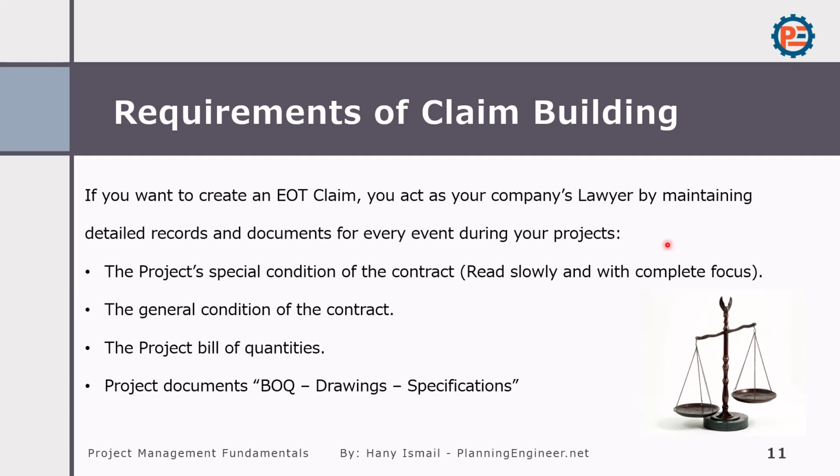I have seen too many claims that it would be very easy for a client or consultant to reject, simply because it is not a complete claim. When we say claim, it is not enough to submit a Primavera time schedule or a couple of pages as an explanation of the claim. There is a structure for the claim, and it should be followed, because when you create an extension of time claim, you assume this claim will go to court. We work for the worst case scenario. So you need to be very clear, because if anyone external to the project reads these documents, he will understand what happened and what the impact is.